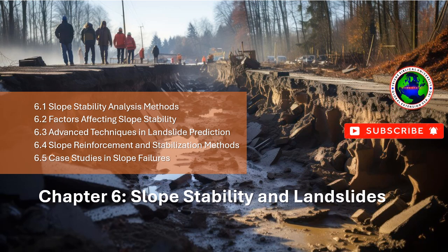Revised design guidelines. The disaster led to the development of new design guidelines for dam construction and the surrounding areas, placing more emphasis on slope stability and detailed geological investigations. Lessons learned.